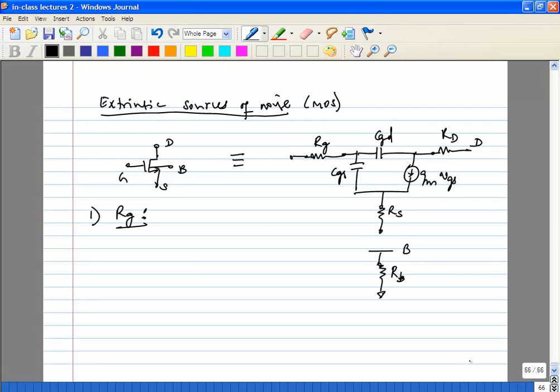So let's say you're contacting down to the substrate, to the transistor drain and transistor source. You'll usually have metal lines, and all you have to do is make sure you have enough contacts to come up to the right metal, and enough metal width for current density and resistance, and you're good to go. Now Rg, it so happens, directly relates to your transistor dimensions. If you have a transistor of a given width and length, drain and source contact through metal directly to the diffusion. The problem with the gate is it contacts from the metal down to poly, which is relatively high resistivity, and then that is the gate. The poly itself is the gate.